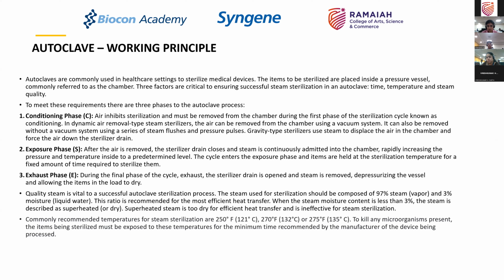The commonly recommended temperatures are, of course, 121, 132, 135. Generally, you choose 121, but that's a saturated steam, and depending on the type of material that you are trying to do, you have to choose the temperatures of the steam accordingly. Generally, the most widely used in the industry is 121, or slightly higher than 121, 123 plus or minus 2,